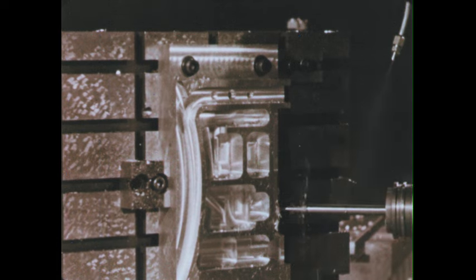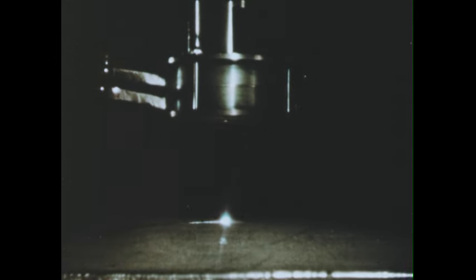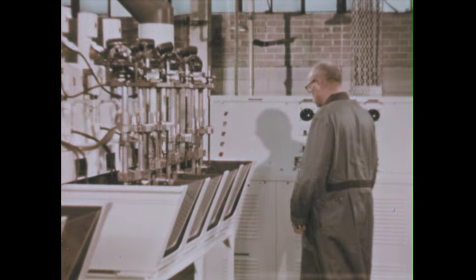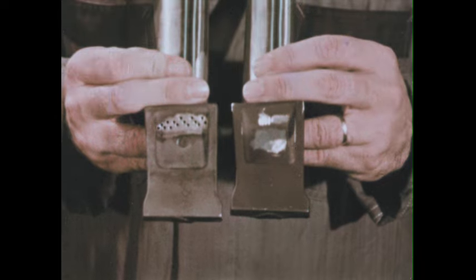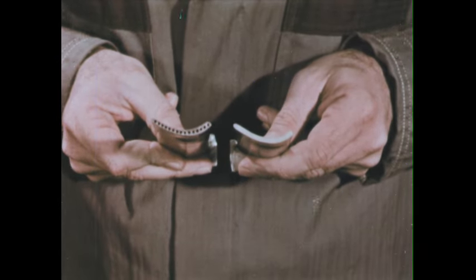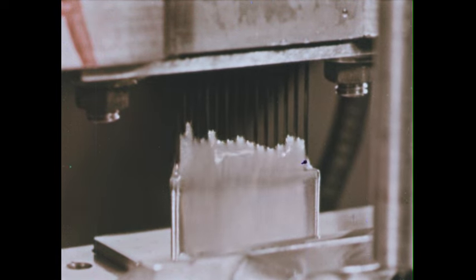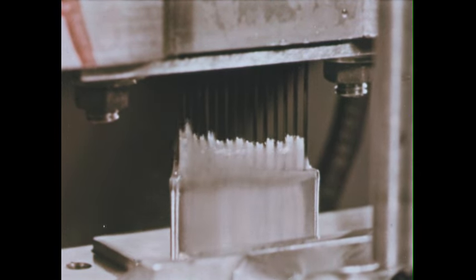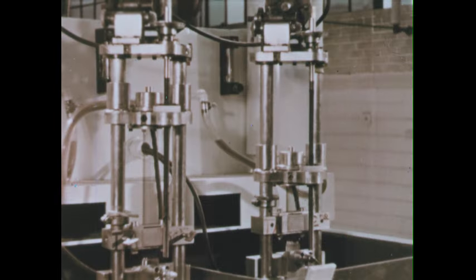That's right. Well, what about the actual joining, forming, or removal of metal? What's new along these lines? Plenty. Electron beam welding, for one thing. Here, even two dissimilar metals can be permanently fused together by the high-velocity electron bombardment in its vacuum chamber. Electrolytic machining, for another. The cooling holes in this turbine blade were eroded to exacting tolerances by this stem drill. The hollow drill electrodes never touch the material, so they need not be reset or replaced.